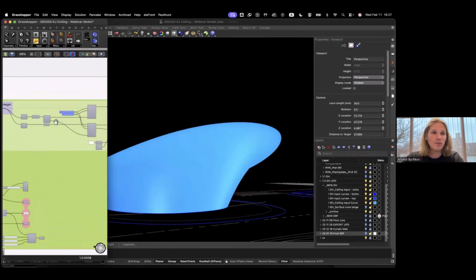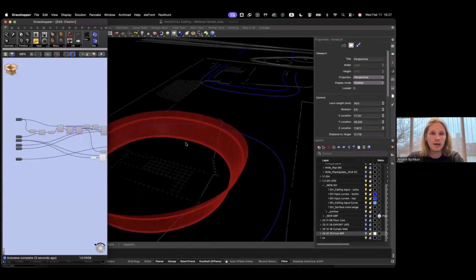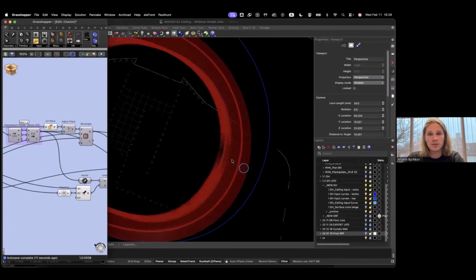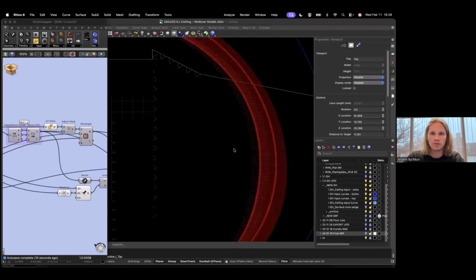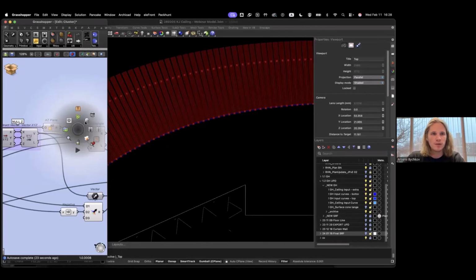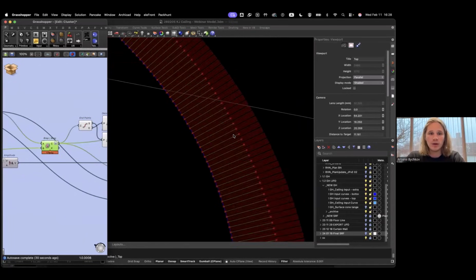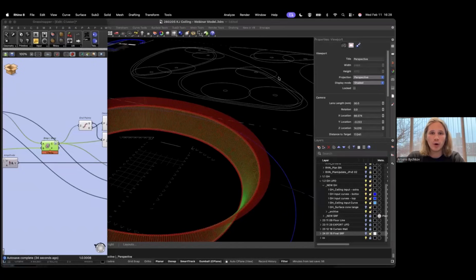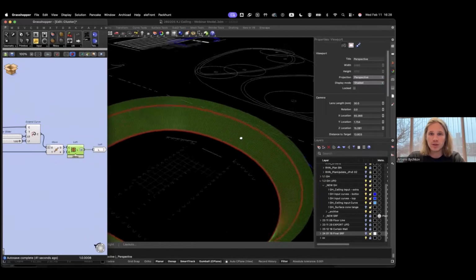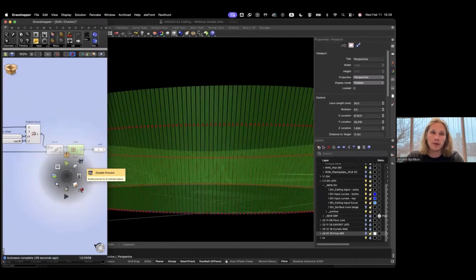And once we were happy with it, we built a small tool. The way it worked was, it was taking the bottom curve, and then it was positioning the planes perpendicularly to this bottom curve. You can see that it should be perpendicular. Oh, sorry, it's here. There we go. And basically what happened next was just a very simple intersection between the surface of the cone and those planes. And then, once again, through a very basic extrusion, those planks were created. And that was already enough for us to see how the planks will develop.